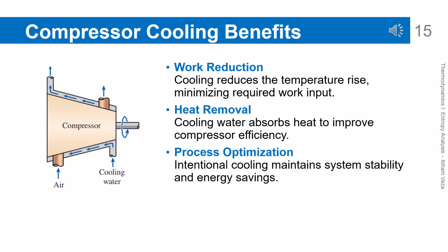Compressor cooling benefits. Cooling in a compressor reduces the temperature rise during the compression process. With a lower temperature, the specific volume of the fluid is also smaller, which reduces the required work. Cooling water absorbs heat from the compressor to improve overall system efficiency. This process also helps maintain operational stability and prevent thermal damage. Therefore, cooling is an important strategy in compression system design.